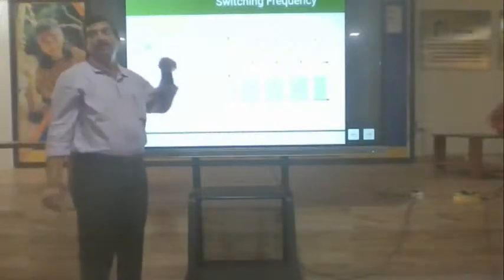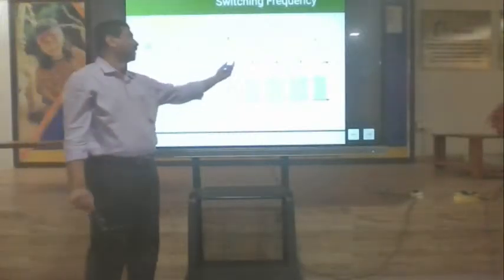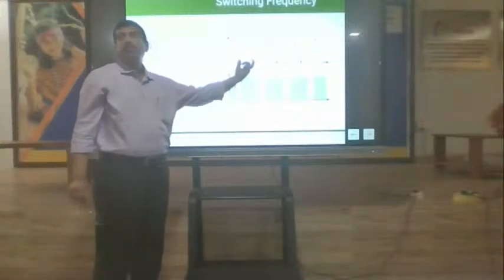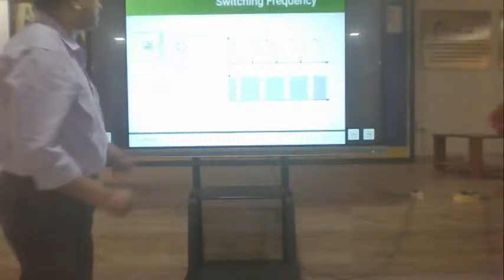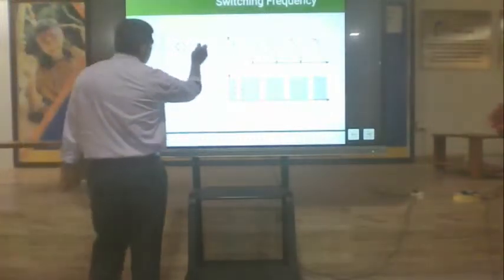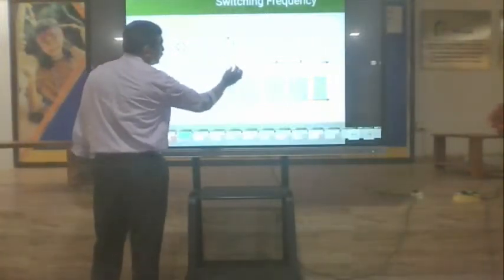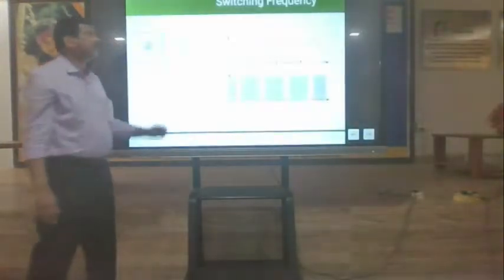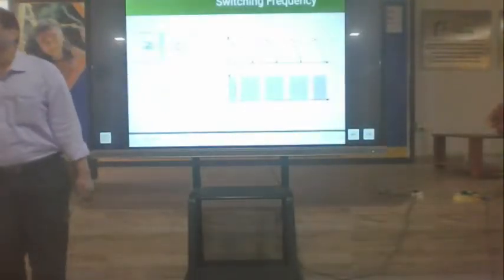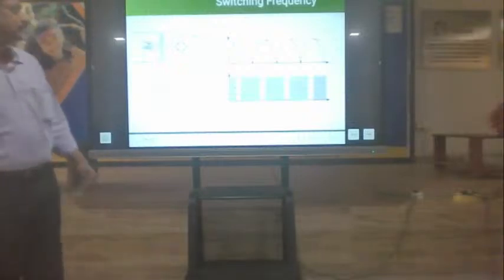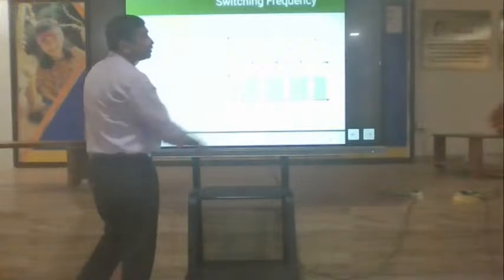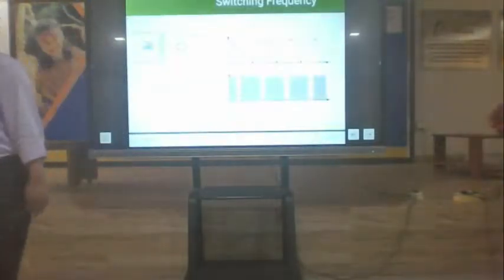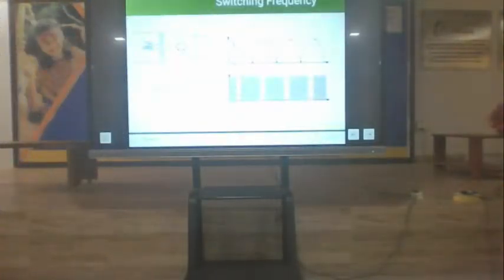The size of the capacitor decreases and the charging interval also decreases. Thereby you can get a much more efficient and better regulated supply. That's why in a DC-DC converter, it is going to be high frequency switching, not low frequency switching.